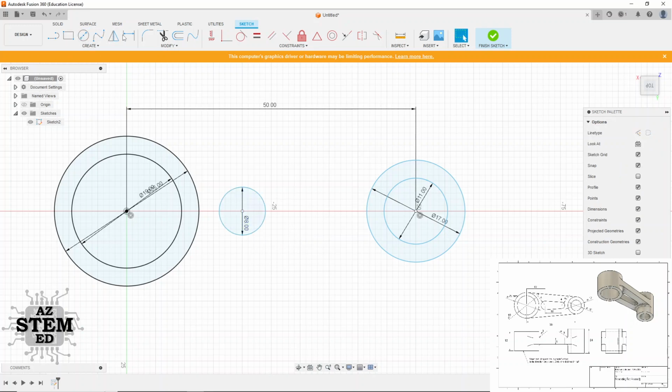I want to put a dimension so I can constrain it to a certain distance. So let's click there, and click this one. That didn't work. Let's try again. So constrain it from here to there. I'm afraid it's going to move one of them, but maybe it won't. Okay, this needs to be 19.